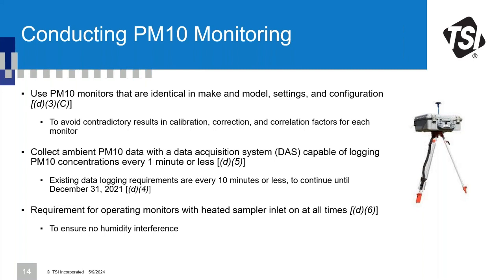So the device itself would collect the PM10 data and then push that out to a data acquisition system. So this is a telemetry option that they're asking for, being able to log every 10 minutes or less. Typically they ask for like a 1 minute average, but they're kind of vague on the exact requirement there. That heated inlet sampler, that's something they require for all the monitors as well, to make sure that humidity does not affect the result.